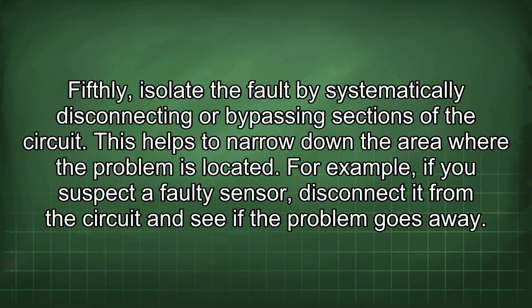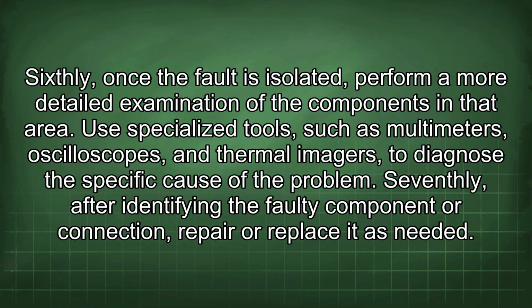For example, if you suspect a faulty sensor, disconnect it from the circuit and see if the problem goes away. Sixthly, once the fault is isolated, perform a more detailed examination of the components in that area. Use specialized tools such as multimeters, oscilloscopes, and thermal imagers to diagnose the specific cause of the problem.